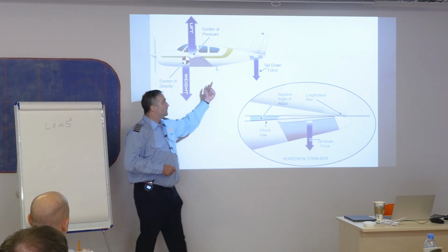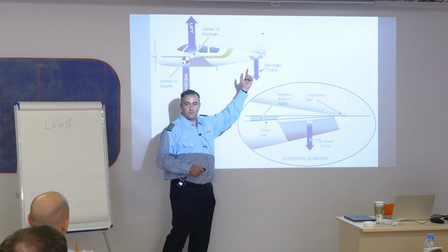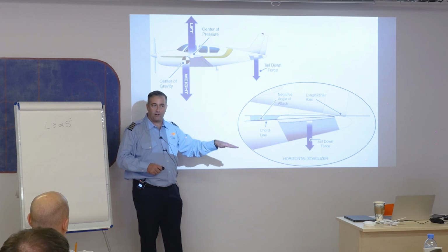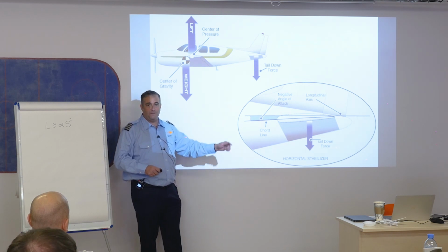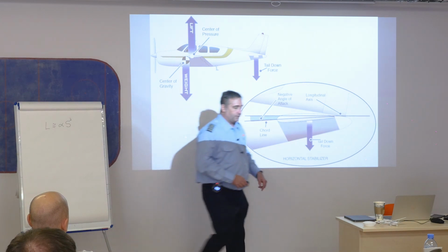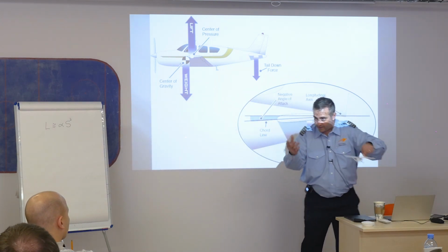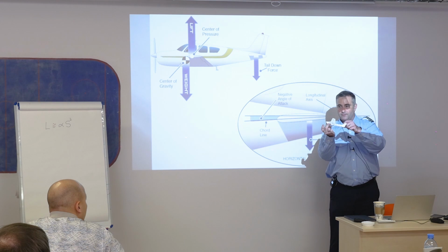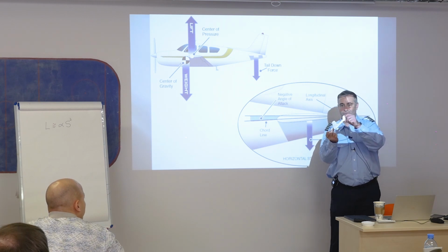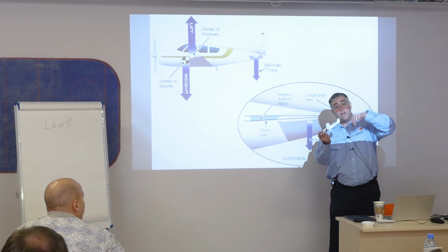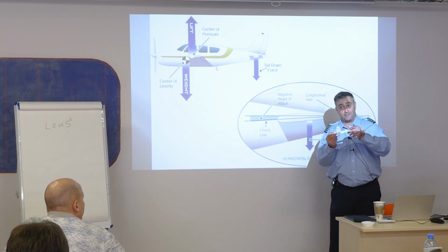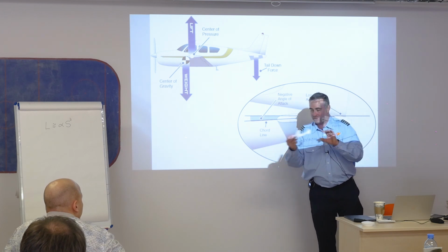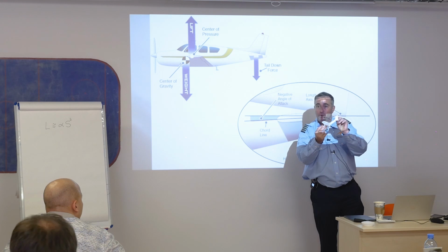That's fine. Lift here is also decreased. So the airplane begins to move downwards, and it begins to accelerate downwards because of gravity. And I also get less tail force. Here's my less tail force idea. If I have less tail force, what does that cause? Pitch down. Okay? I still have tail force, but there's less. So effectively, I have a lifting force back there. Right? The tail of the airplane will move up.